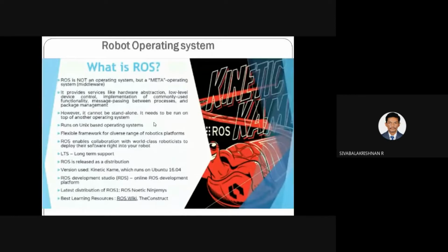The arm motion is referred to the base of the robot, but the object is referred to the camera reference. So you have to convert the object position transformation matrix into the robot base transformation, referring to the object position in terms of the base of the robot. For that, the controller will take care of transforming the position reference.